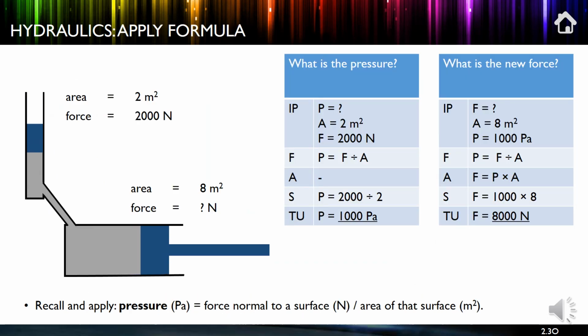So here we have a typical answer. Again, freeze it if you want to, pause the video if you want to see the detail. But in essence, we can work out the pressure here. So we've got area, we've got force, we can work out the pressure. We know the pressure must be the same here, and because we know the area, we can work out the force that's being created.